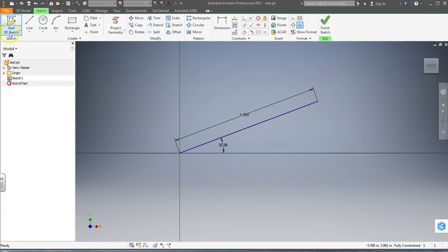So if I'm going to make another line, I'm going to come down, I'll snap. Notice the little green thing. If there's no little green thing connecting, it is not touching. If it's not touching and it's not a fully closed entity, it is not going to be able to be made into 3D.